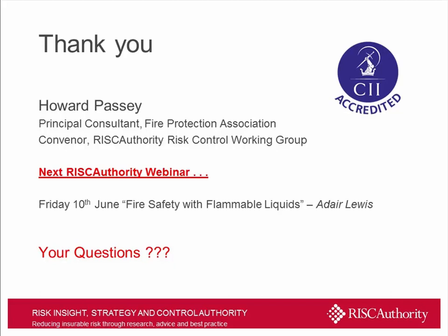We've come across a number of occasions now where certain sites, I think the new build at Heathrow T5, had one day a week where they wouldn't take any deliveries onto the site, and time was spent by the general workforce ensuring that any combustible waste and packaging and suchlike was effectively cleared from the site, and that where they were introducing materials that were going to be used during the construction phase that were combustible in nature, they were being effectively protected. So, yes, thank you for that comment.